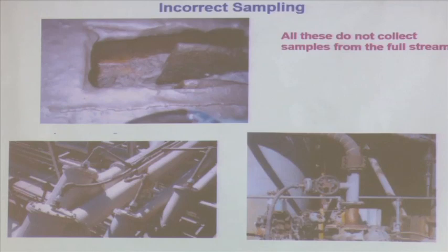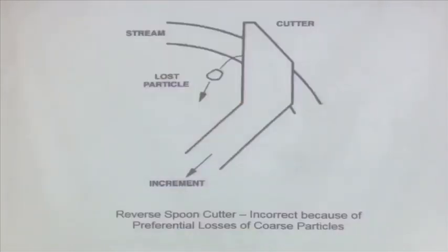think of, based on your planning of sampling requirement, you can have a cross cutter. You have to cut the entire cross section of that, otherwise your sampling will introduce a bias. Okay. That is a correct sampling procedure. This is what I said, that if your cutter is not properly designed, or maybe the moving speed is very high, you may miss some of the particles that may go out from the system.